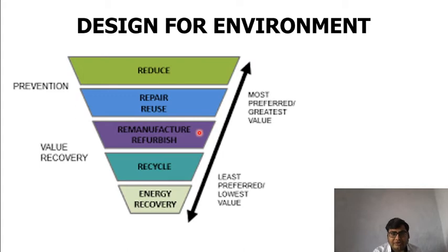What modular design will do is help us identify the exact pinpoint where we can simply remove a damaged component and place a new component, so that it can be remanufactured very easily, and we do not need to open up the entire product. So we can change our design to make the product more remanufacturable.